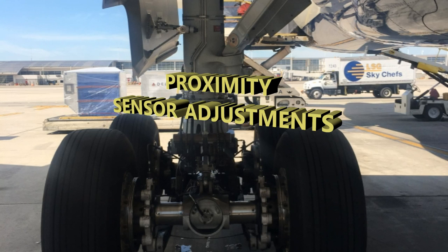You can also use the shims, calipers, or anything else that they may specify for you to measure the gap. And you can again use the shims to get the necessary gap. So you're making those proximity sensor adjustments to have that measured gap.